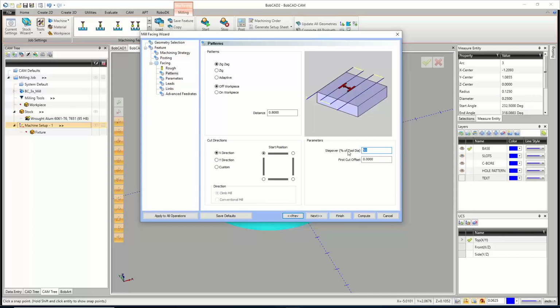And if you guys do look at that GWizard program, I would also just suggest signing up for his newsletter. It's weekly, but he's got a lot of good tips and tricks. One of them that I spotted, I think last year or so, talks specifically about 50% step overs and how your tool just hates having that leading edge of the cut right at the center of the cut.